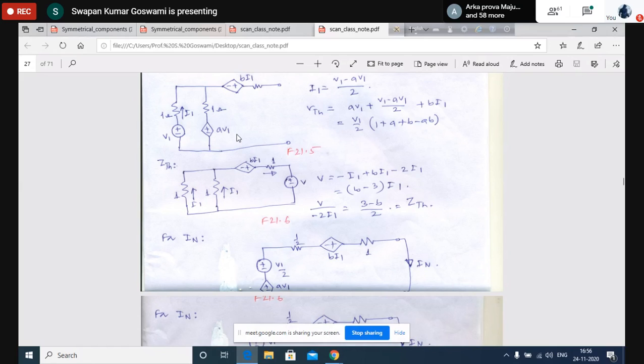All right. Now the remaining portion is very simple, because you now calculate the Thevenin impedance here. How? You calculate the current delivered by this source. How to calculate this? You can write a loop equation here. Either you write a loop equation for this loop or for this loop. Whatever equation you write, obviously you will be able to calculate the current.